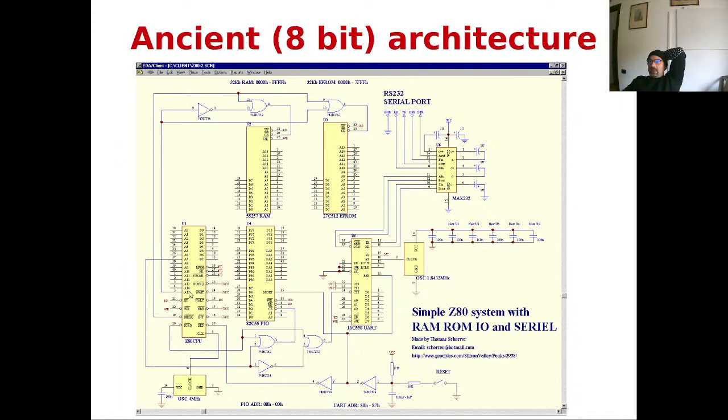Besides the CPU, this is the bare minimum, but our architecture wouldn't be able to communicate with the outside world, so it would basically be a closed box computer. In order to interact with it, we need to couple it with a parallel input-output, which is basically a digital port, which you see here, and the UART, which is a serial port, which is here. They are typically memory mapped, or they appear as memory locations to the CPU, still by playing with the decoding of the address bus. So basically by having some logic that treats the highest pins of the address bus and decides which chip to enable, while the low pins of the address bus are devoted to assigning the address within the chip.